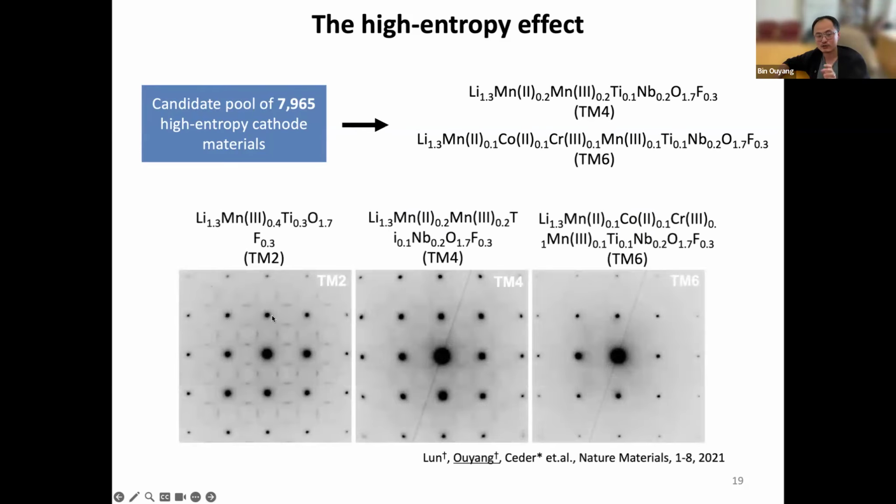The first thing we do is electron diffraction, and we do see that with 2 transition metals, you're going to have short-range order features, but as you gradually add metals into it, the short-range order features disappear. I would not argue that it's totally disappeared. This is still an unsolved question in the field of alloys, but at least you cannot see it very obviously. That's good enough for us.